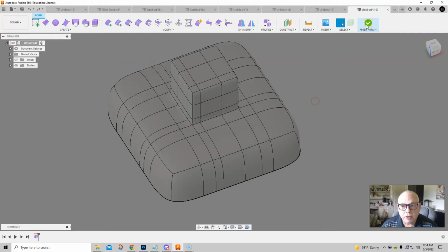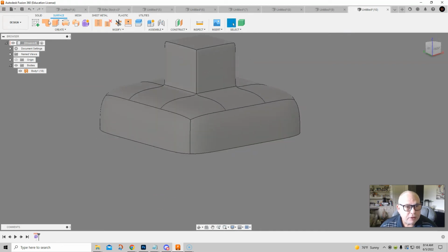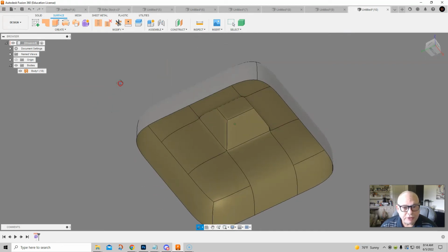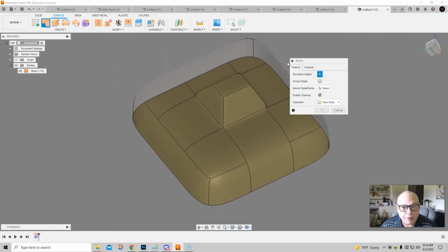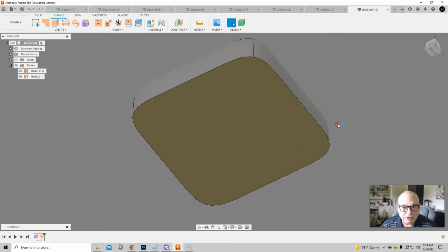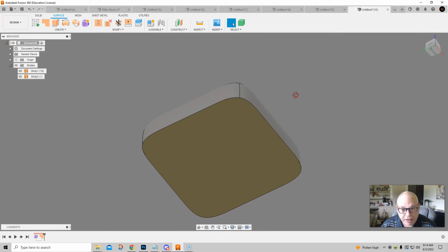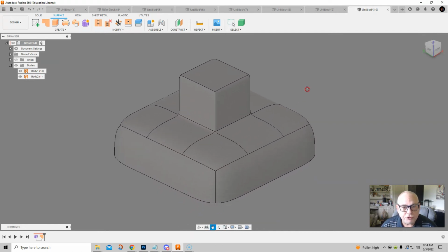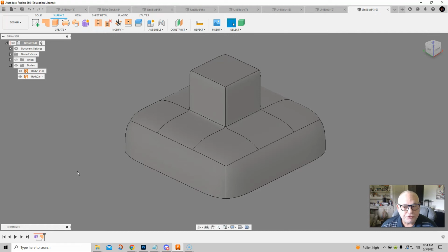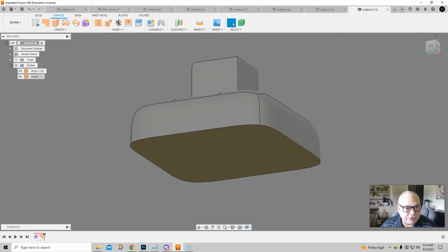So, okay, we're going to go ahead and finish this form. And now that we're in our surfaces, what you can do is patch that. All we have to do is go to Patch and click this, and then it's going to patch this. Surface is a modeling process inside of Fusion 360 where you can make surfaces. They don't have to be three-dimensional. So I can surface this. Now, when I do this, you'll see that it makes two of them because this is a separate piece.